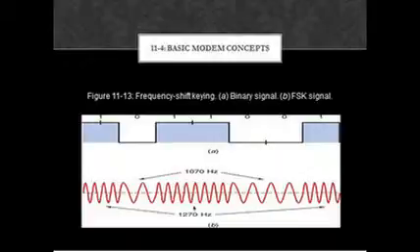wherein A is a binary signal and B is a frequency shift keying signal. These two frequencies are alternately transmitted to create a serial binary data. The resulting signal looks something like that shown in Figure 11.13. Both of the frequencies are well within the 300 to 3000 Hz bandwidth normally associated with the phone system.